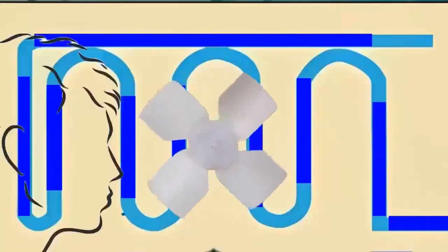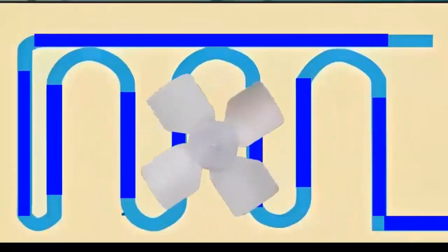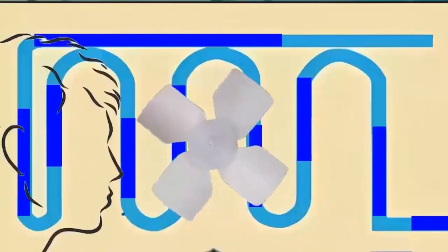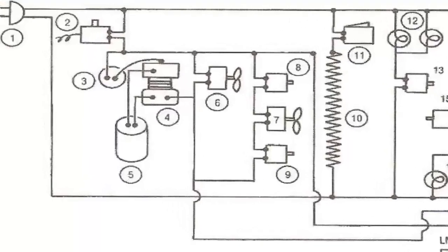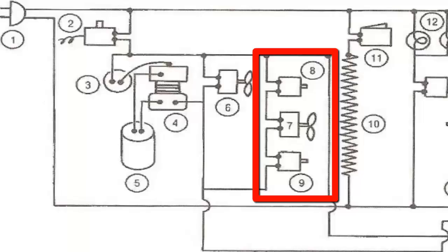3. Check the freezer fan. Make sure the freezer fan is spinning correctly. Remember that some refrigerators have a switch that disconnects the fan when the door is open. Find this switch and press it to check if the fan works when the door is closed.